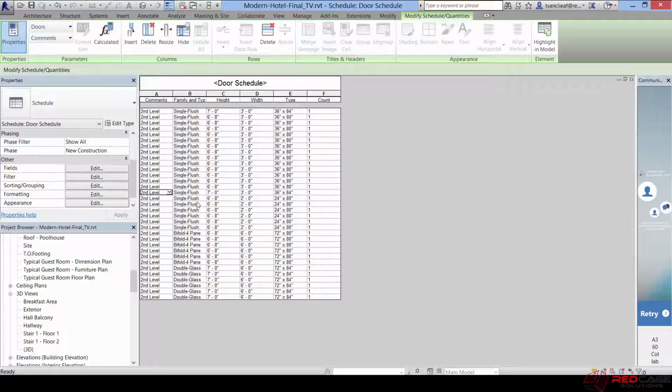So that's just a quick illustration of some of the ways that you can leverage data from your model and interrogate your work. If you've got that data, do you want to go around and count manually? You could select an instance and do that, but you might not get everything. So if you filter and select all doors by category, you're able to apply certain information to it that you can use down the road for other commands, essentially.